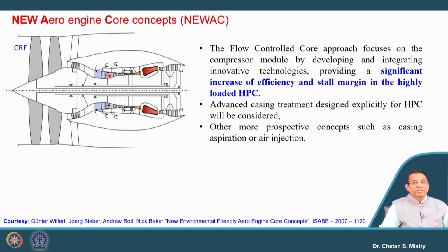Okay, and that is giving a new kind of inclination, where we will have a new concept of casing treatment, aspiration, air injection. All those possibilities are being explored. So we will get the benefit of the counter rotating fan configuration with these additional devices. When we incorporate these additional devices for control, it is obvious that it makes our system more complex, and it requires a lot of attention.